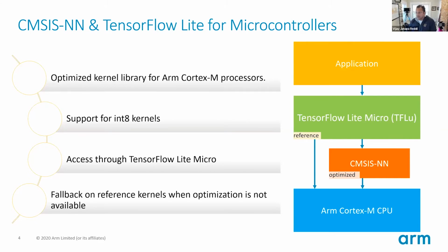So in a similar vein, is the goal here for CMSIS-NN to, well, if a framework like TF-Lite Micro supports it, then okay, we'll provide all the necessary optimizations, or is there some way you would even distill that? We look at the models that are popular in the field currently, and then we look at the operators that consume the most cycles in those networks, and decide the operators that we pick from the wider subset. Does that make sense? Yeah.